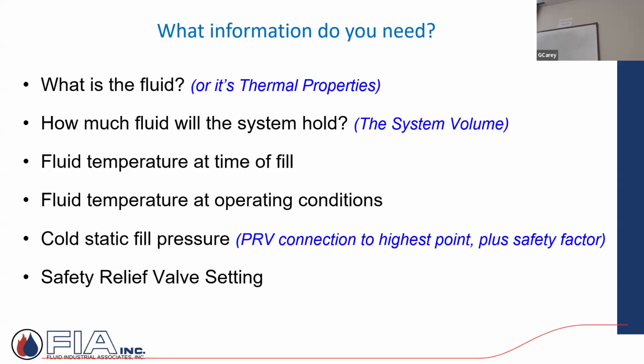So expansion tanks, right? Really important. Kind of elusive sometimes or sit off to the side. Very important. So what information? What's the fluid? How much? What's the volume? What's the temperature when it's cold? What's the temperature when it's operating? What's the fill pressure? What's the relief valve? So temperature in, beginning and end, fill pressure and relief, and what's the volume?